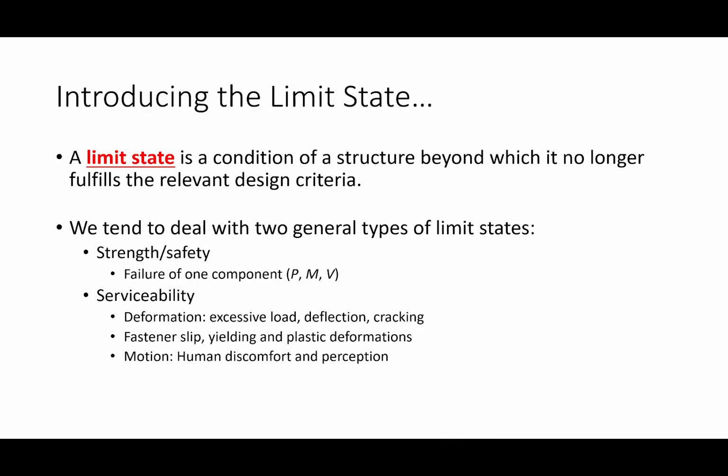I could design every single beam according to the lightest weight possible, and what I might end up with is a Rubik's Cube of a frame with 500 different beams. That might be really difficult to put together. It might be easier to take those 500 shapes and whittle them down into half a dozen or so that just get repeated over and over again around the building.